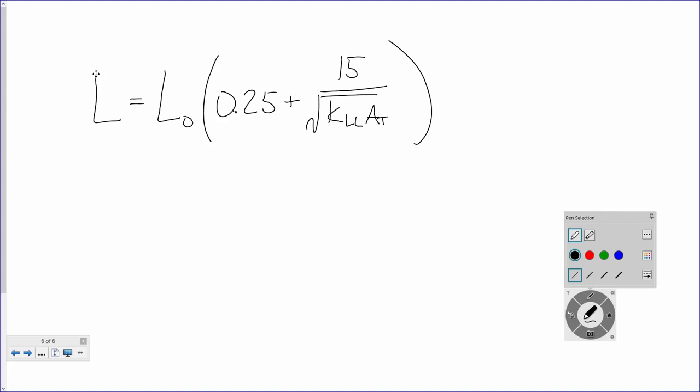So for those of you that weren't exposed to this, this is the live load reduction formula used to account for building loads. To give you an idea, if I remember correctly, the design load for a classroom, let's say, I think it's like 40 PSF. I think it's 40. It might be 60, but I can't remember. Now, to equate that in terms of people, the size of this room, to reach that design load, you'd probably need about 120 people in this room. When do you ever think there's going to be 120 people in this room?